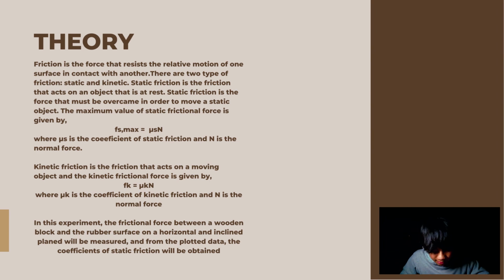In this experiment, the frictional force between a wooden block and the rubber surface on a horizontal and inclined plane will be measured, and from the plotted data, the coefficient of static friction will be obtained.